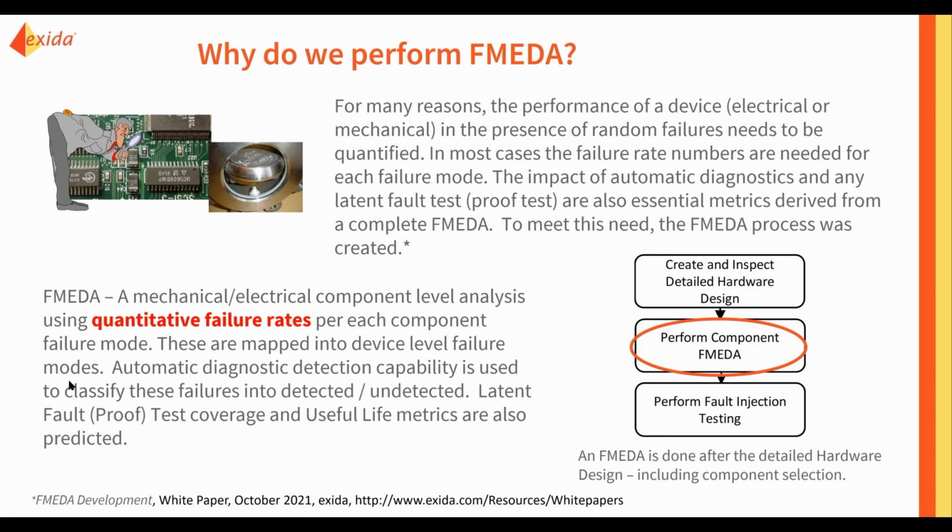An FMEDA is defined as, let's say, a component level bottom-up analysis using quantitative failure rates for each component and each component failure mode. These are mapped into the device level failure modes, each component contributing a certain amount to each device level mode.